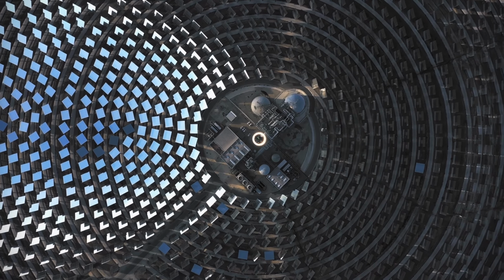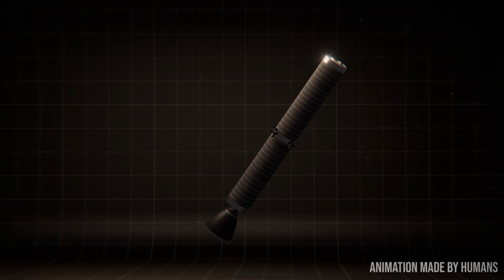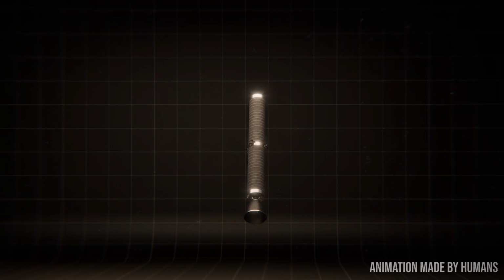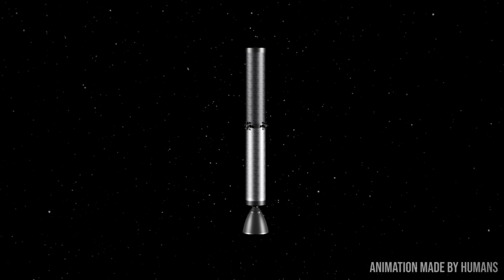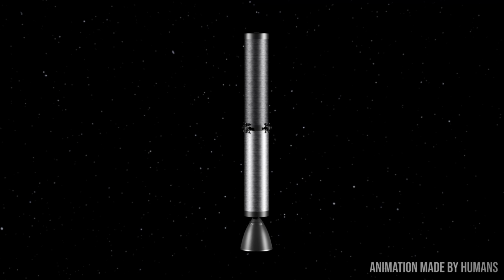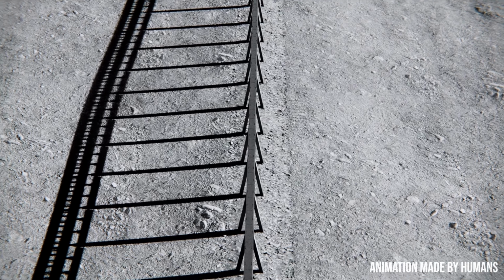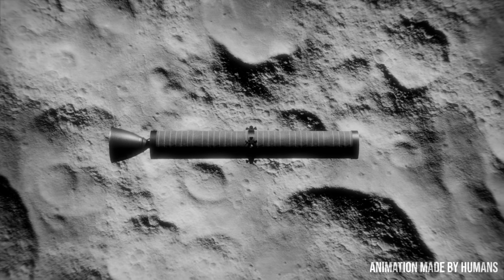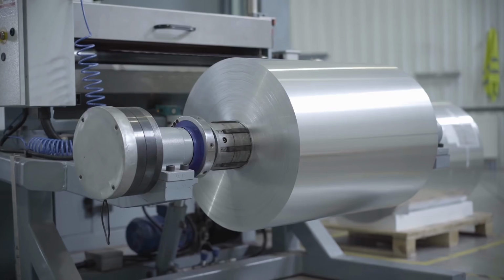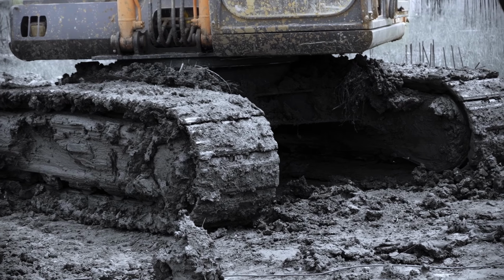But we have two solutions to reduce it. We can either lower the acceleration and thus increase the length of the track, or we can lower the mass per shot by shrinking the size of the mass driver rocket pods. And long story short, shrinking the size of the rocket pod to lower mass is the better option of the two, because decreasing acceleration will increase the size of the mass driver, since track length scales roughly as 1 over acceleration. So you are gaining lower peak power, but paying for it with more track length, which means more refined materials for rails and supports and power electronics and more terrain preparation and everything else.